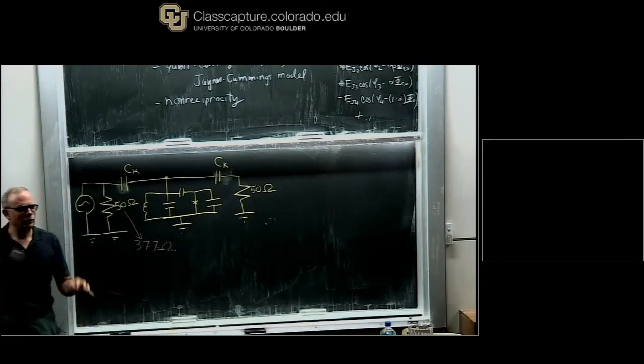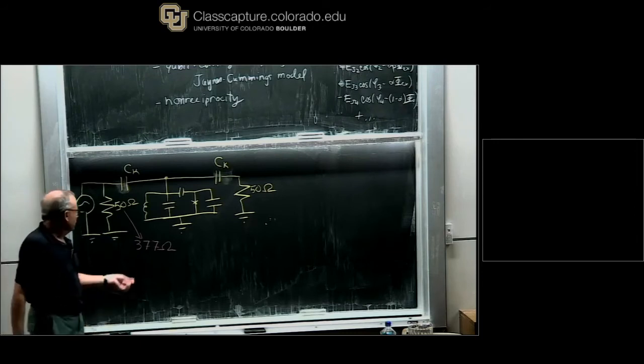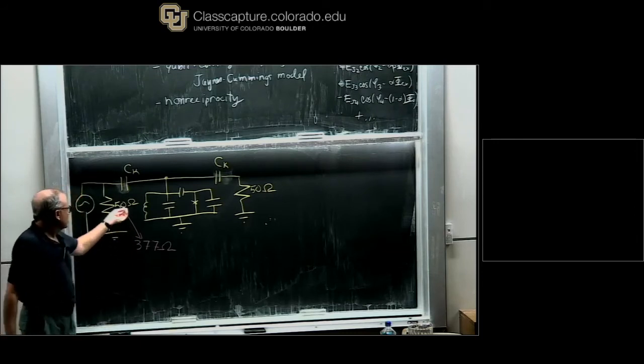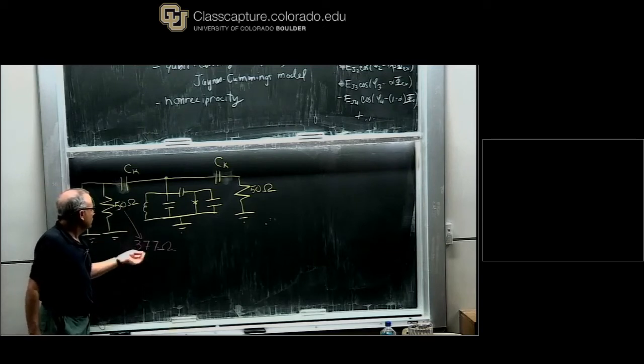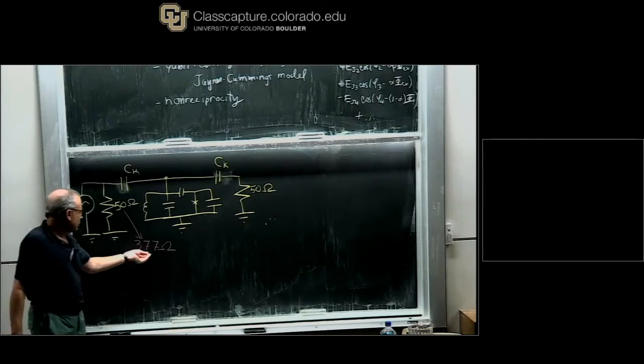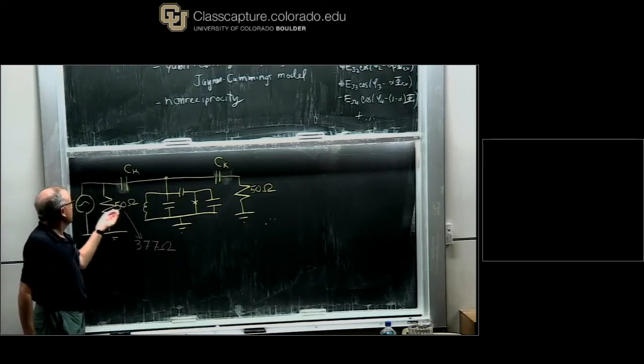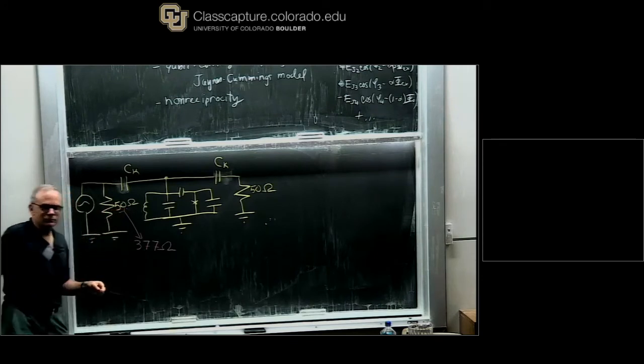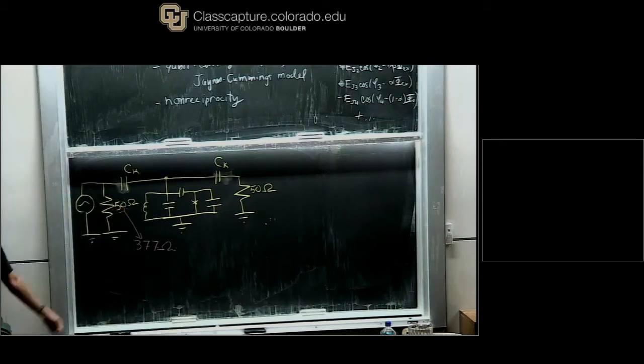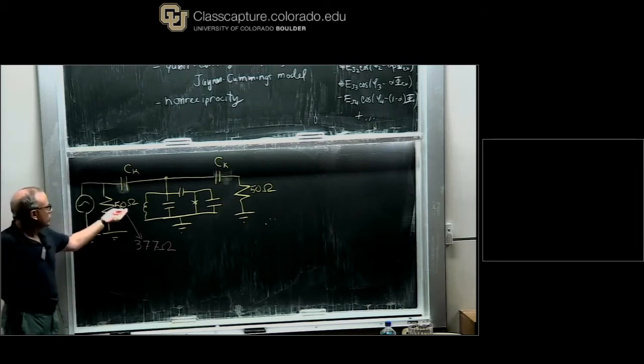I suspect half of you know this story, but it's always worth revisiting: the engineering number 50 ohms is what it is because it's not very far from what it, quote, wants to be, which for waves in vacuum would be 377 ohms. This comes from a standardization, and actually there are 75 ohm systems. But it couldn't be millions of ohms, or a micro ohm. Our medium for carrying electromagnetic waves wouldn't want to have such a different impedance. So these are typically 50 ohms.